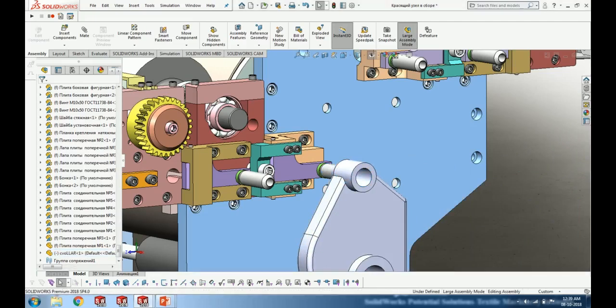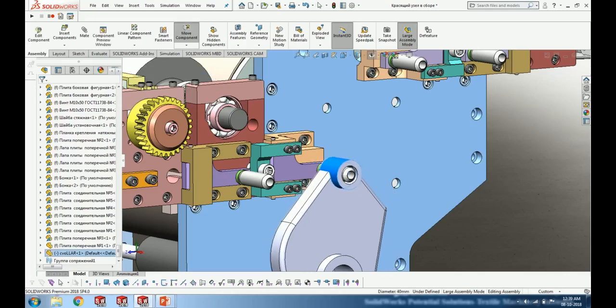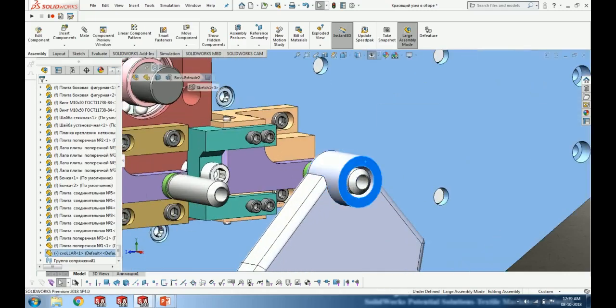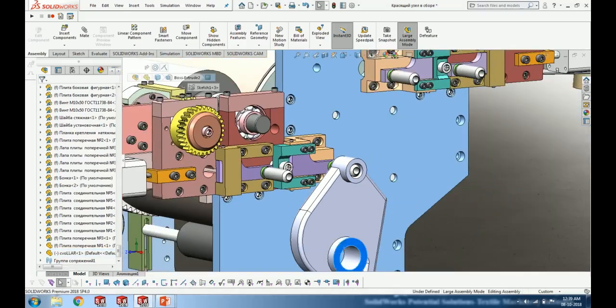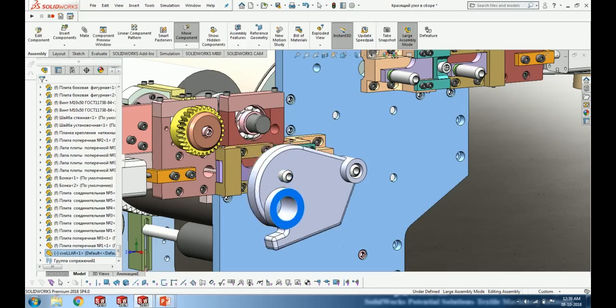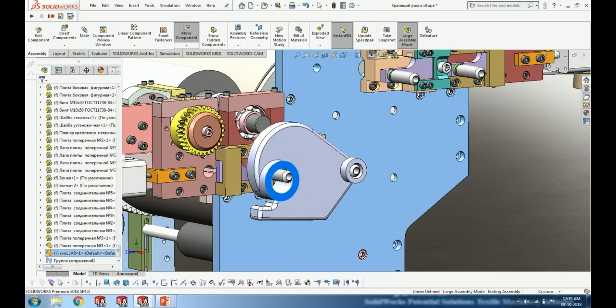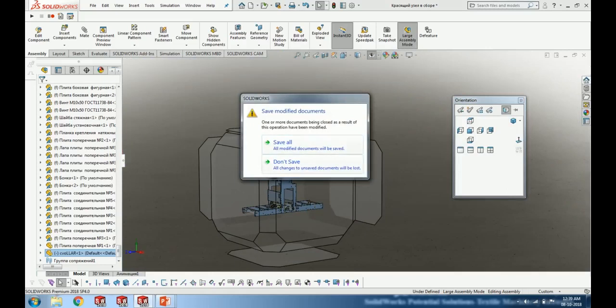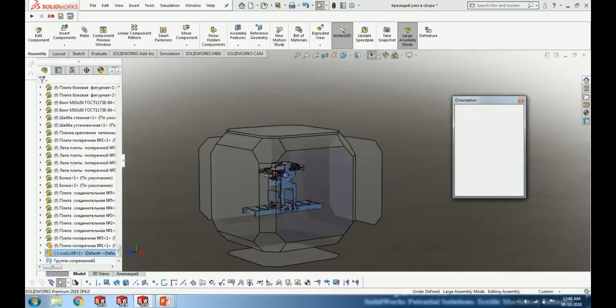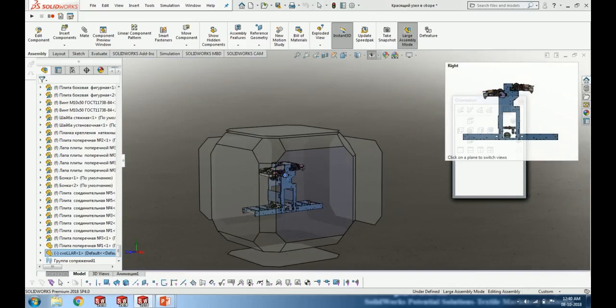I make a concentric mate to this part, and here you can see that these two edges should be coincident to that. I have fixed one end, but at the other end you can see that it is a movable component. The up and down actions should be movable, so that it can be mated with the other component. Any clearance between the two components can also be identified using the evaluation tools like interference detection, collision detection, and hole misalignments.